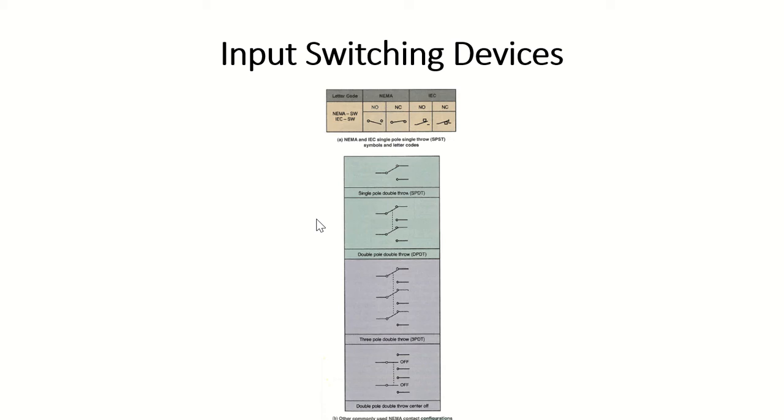So what I did was I went up in those light fixtures and wired them for 240, and I had to get a double pole single throw switch. So a little bit different than this double pole double throw. It only had one contact position, kind of like this top symbol here. But that's an example where you'd see a double pole switch. And then typically a 3-pole switch would be used to make or break 3-phase equipment. And you'll see a whole bunch of different ones in between.